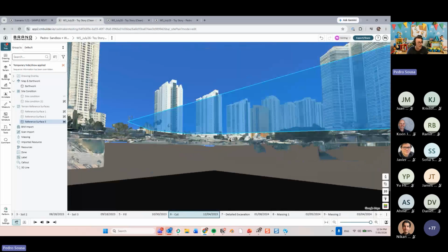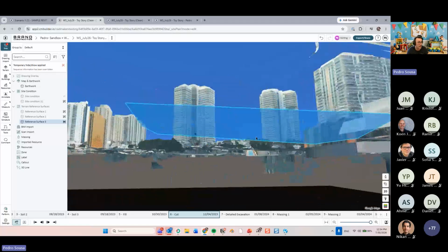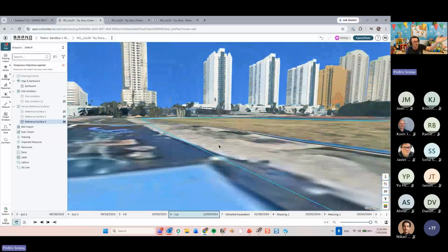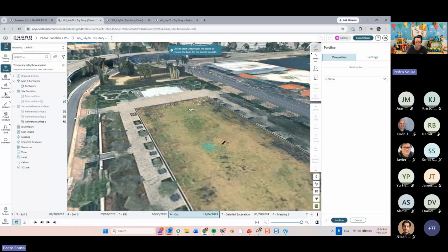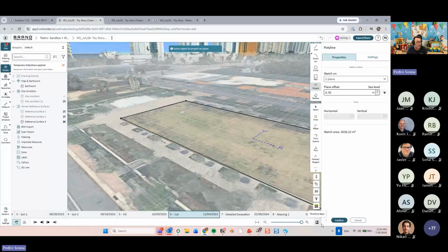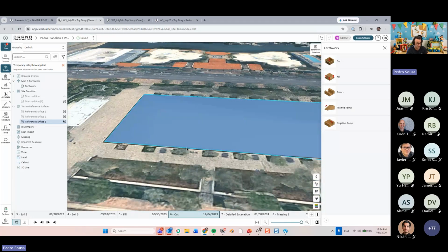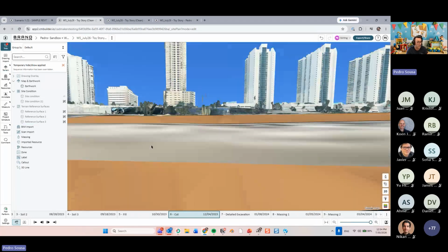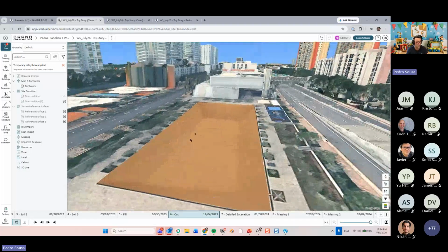As you can see, it has a slope. It has a bottom, kind of like a sloped bottom over there. It has sloped walls. And then I can go over there in my earthwork, cut, same idea. Project this guy, and then hit confirm. Follow that shape. Offset is 0. There you go. And then I have now my cut over there that has a bottom surface, right? So a sloped surface at the bottom.